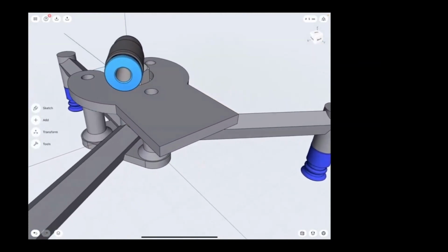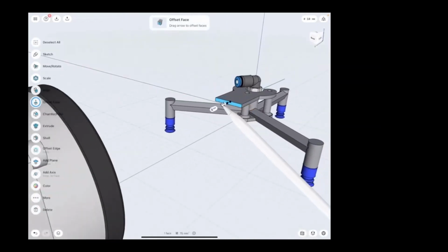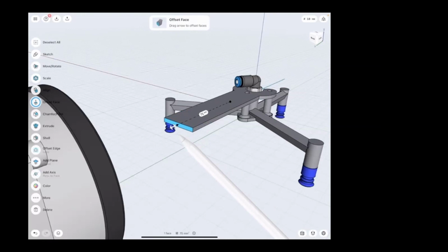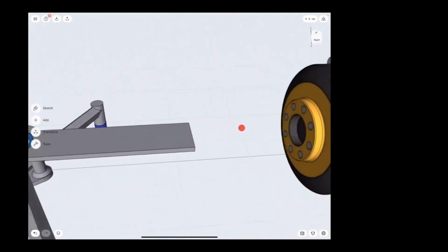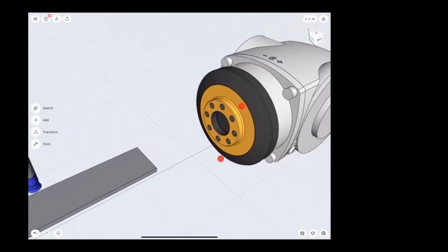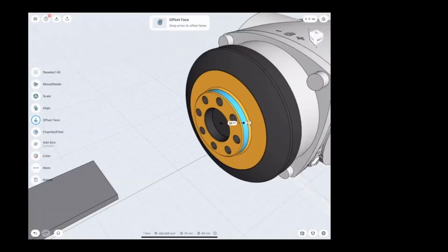The shape is almost ready, but the handle is quite short, so let me make it longer by moving that face by 70 millimeter. And then we have arrived to the 3rd part that is designed in the workspace. The orange parts on the robotic arm are standard parts published by the manufacturer of the robotic arm to make sure that 3rd-party manufacturers are able to create accessories for their robotic arms. I will use that cylindrical shape as a reference in the following.